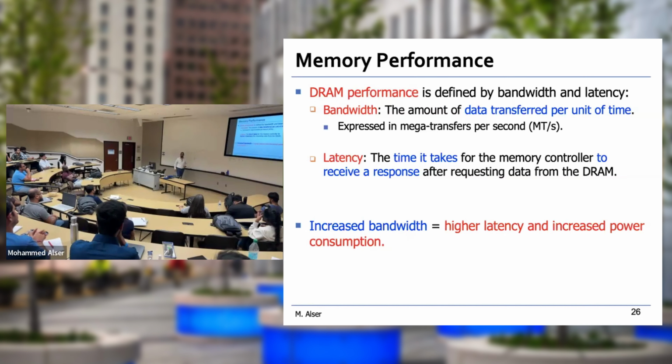Excellent. Or what if I change the row size? Now the row size becomes larger, right? Imagine I change the architecture of the DRAM. I make the row larger, and the chip now is providing, instead of 8 bits, 16 bits, for example. What will happen? I need a decoder that is larger, right? That's in terms of number of columns because I increase the size of the row.